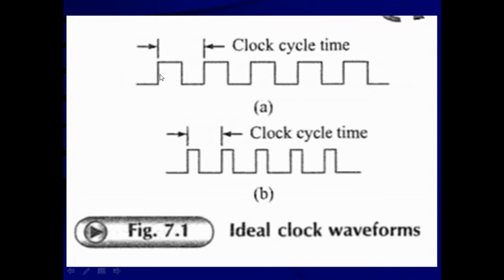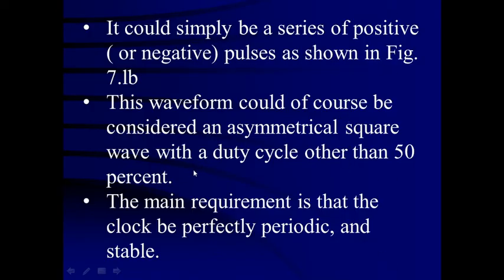So this is called a positive waveform or positive pulses, here or here also. But if it is passed through an inverter or a NOT gate, you will get a negative level. That means the time during which it is high will be more, and the time during which it is low will be less. So just the complement of this signal, or the mirror image of this one, is called negative pulses.